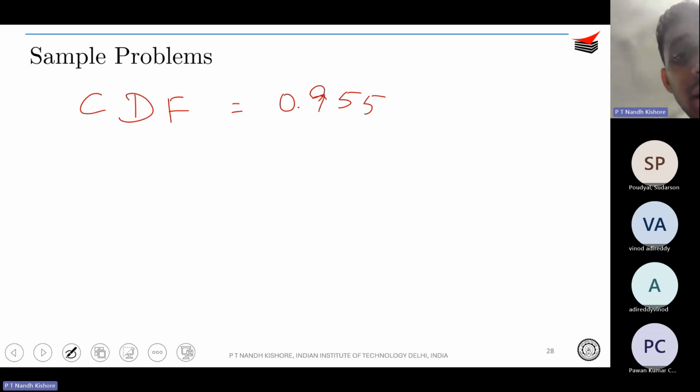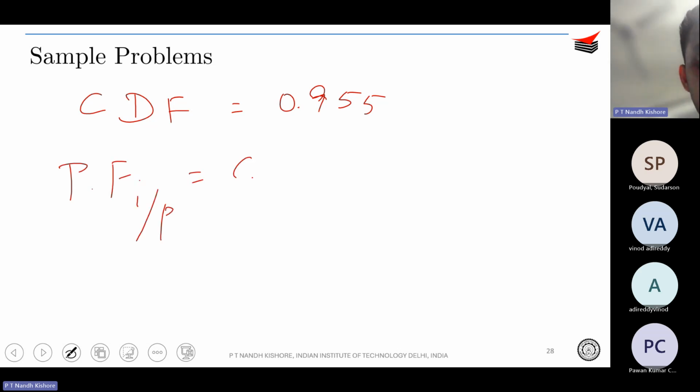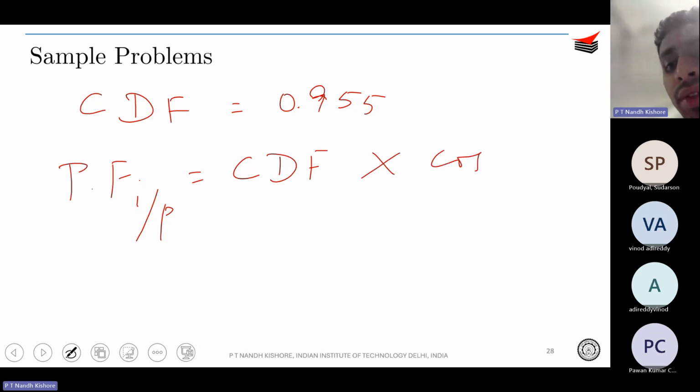If you go through the basic definitions that you saw in, I think, week 2, over there you saw what the input power factor was, how it was related to the current distortion factor and your firing angle. In that, one of them was that the input power factor is actually current distortion factor times cos alpha, cos of the firing angle. Okay.